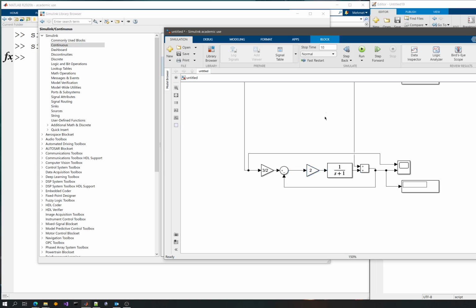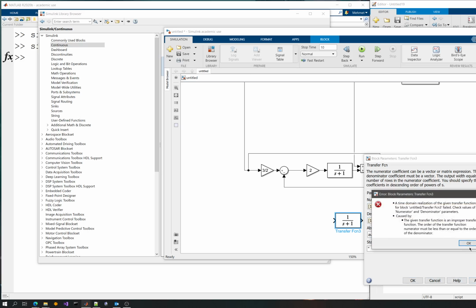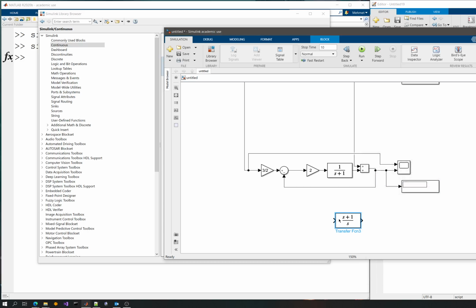Let's have this gain, and let's add also an integrator, or maybe we should add a transfer function. So basically I should copy this, paste this, and let's come up with an integral control. I'm sorry, it should be 0. Okay, now you can see that this is a PI controller. Since I have that, I don't need the gain anymore. I can just plug this in here. I might want to make it like this. There we go. This should be a PI controller, since it is